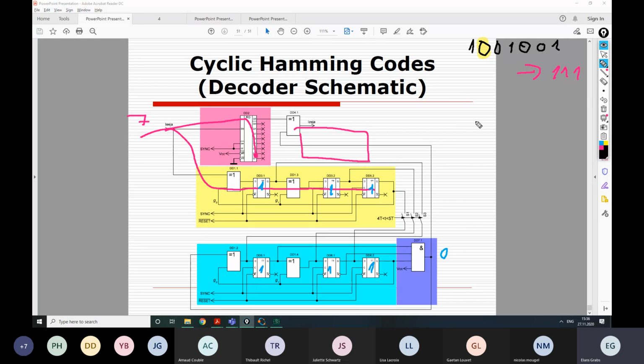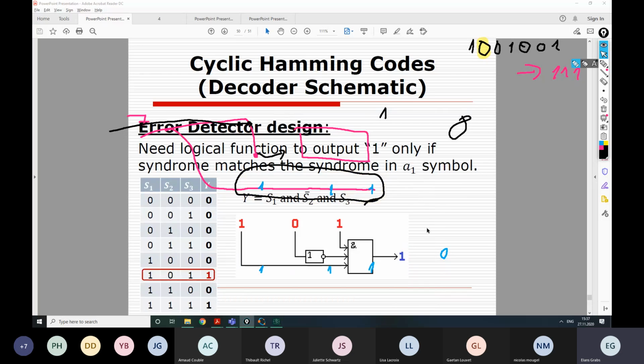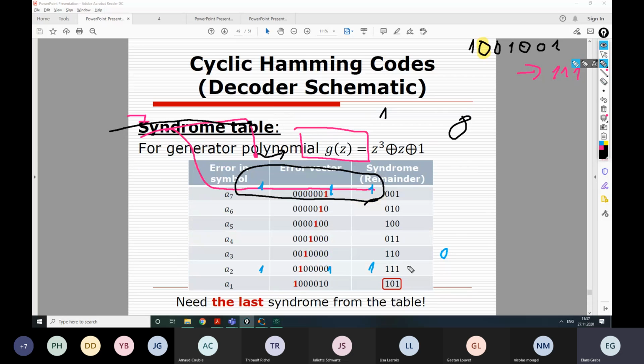So what happens at the time interval 8 is that the first symbol of the data comes both in this register, forcing to leave the first symbol of our previous code word, that would be 1, and start the dividing procedure here. At the same time, this schematic will continue a division and will advance from this to this, right?